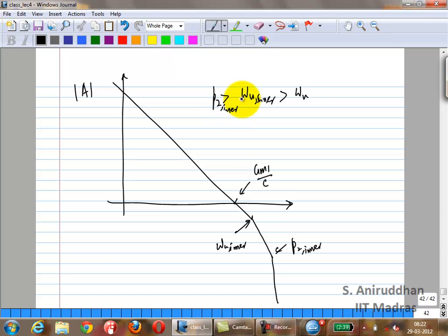So it looks like you have a system with one dominant pole because of C, and then the first non-dominant pole is because of C prime. The second non-dominant pole is because of the P2 of the inner loop. Of course right now we have not considered zeros, and there will be other poles also. There will be a P2 for the outer loop also. We are not looking at all of those. But fundamentally the poles of A over 1 plus A are appearing in the output. Those are the extra poles.